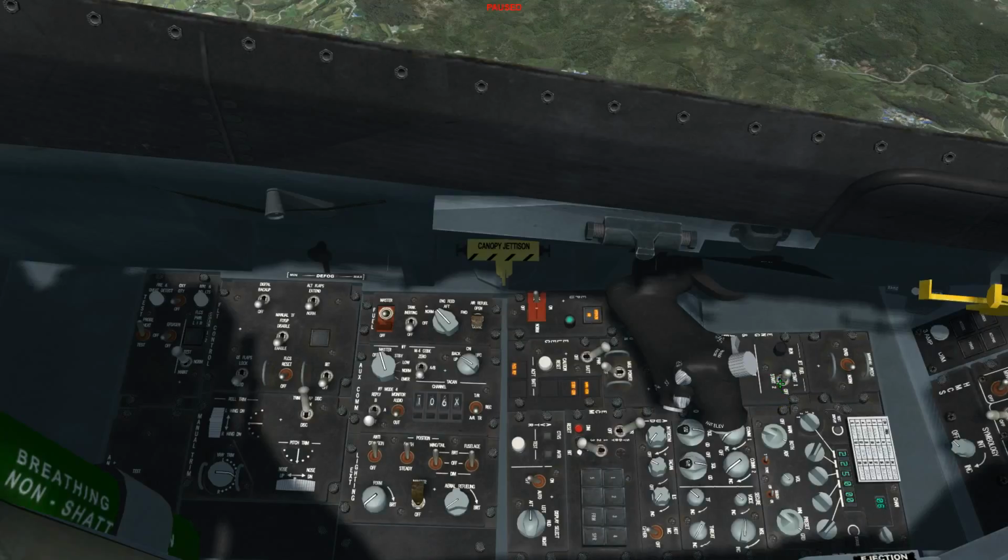But once you've positioned this switch to start, in other words, you either right click it or accidentally left clicked it, you have shot your wad here. You've used the hydraulic pressure in those two accumulators. Because you were above 20,000 feet, it never started, but you used the accumulator pressure. Now you've got no way to recharge this system.